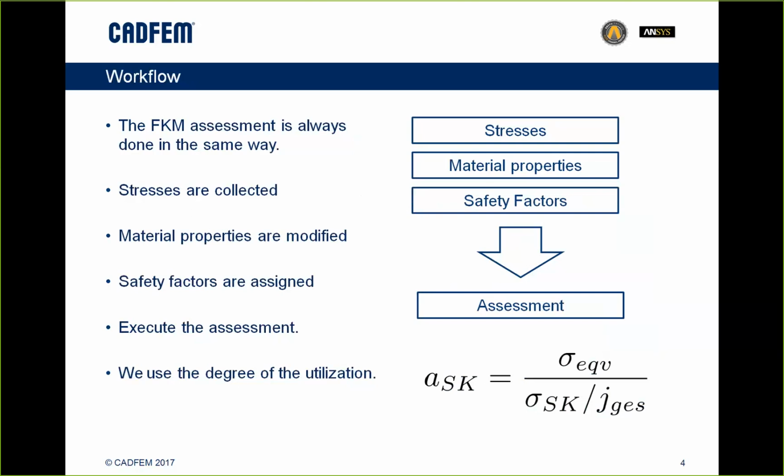And the point is, when I have a small sample, I can produce that really well, especially when I make some kind of heat treatment. I can control the heat on a 1 centimeter part pretty accurately. If I had a 1 meter part, so 1 meter in diameter, and I heated that up so it would really be glowing, and I tried to cool it down, I would see that I no longer have the temperature control, because this big chunk of metal won't be cooled down easily. So I only get the surface cool, and the core will still be awfully hot.